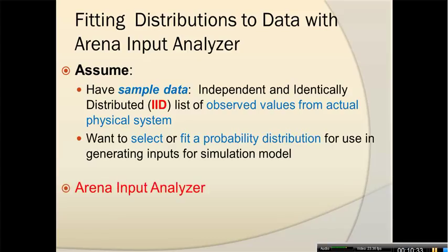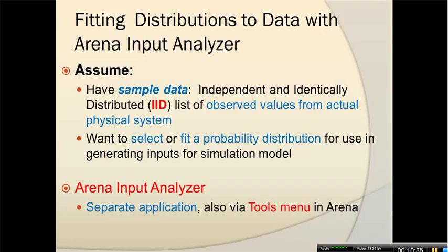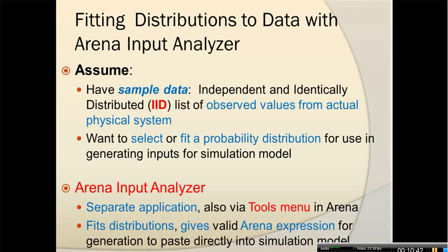So Arena Input Analyzer is a separate application, but you can also reach it via the Tools menu in Arena, and I'll demonstrate that. What it does is allow us to fit distributions and also give valid Arena expressions for generation so that you can directly paste it into your simulation model. So let me go ahead and open the Arena Input Analyzer and demonstrate some of its functionality.